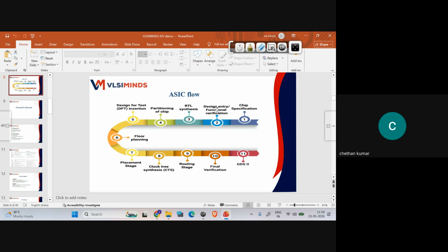After that, the verification engineer is going to verify that. Once he verifies successfully, it goes to the synthesis team. That means they will convert the coding part into the physical part, gate level netlist, structural format. Once that is done, it will be sent to the DFT team and validation team. So the chip will undergo different tests, both in physical format and along with some other things that the chip has to meet.